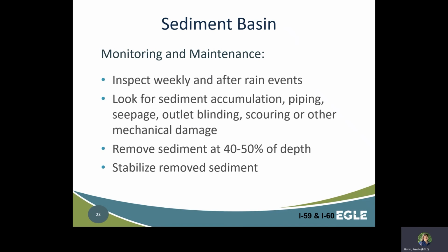Sediment basins need to be cleaned out when a sediment depth of 40 to 50% of the depth of the basin is reached. You may notice a pattern here. Several BMPs discussed in this training program need to be cleaned out when 40 to 50% full.